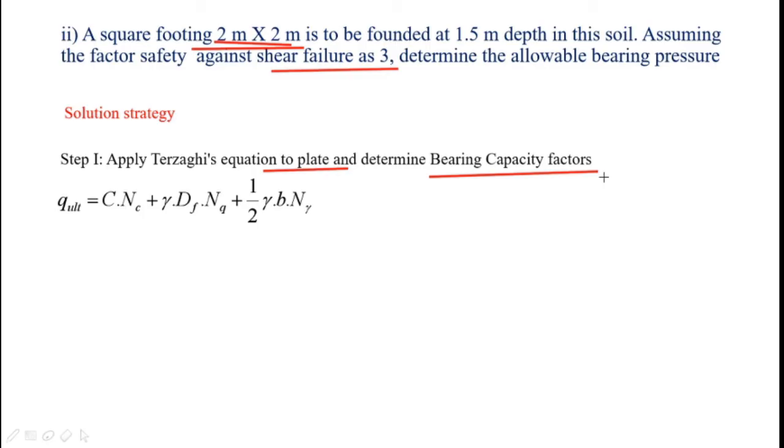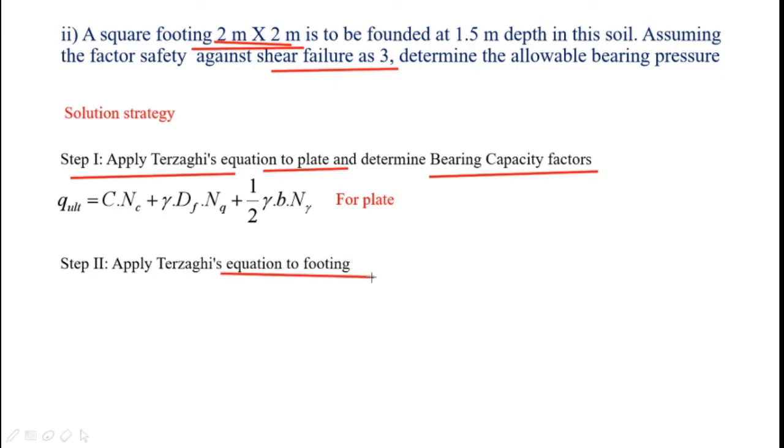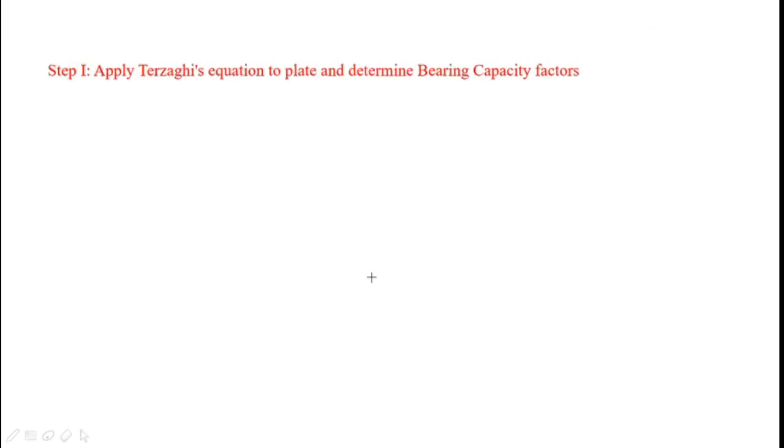Once we determine the bearing capacity factors, we can apply Terzaghi's equation to the soil, to the foundation. In step 1, we'll apply Terzaghi's equation to the plate. In step 2, we'll apply Terzaghi's equation to the footing and determine the bearing capacity of the soil. So let's see step number 1.